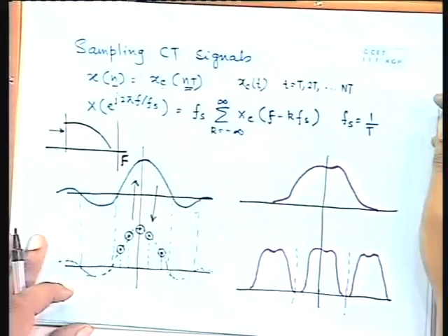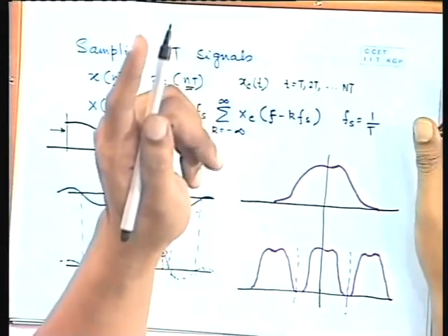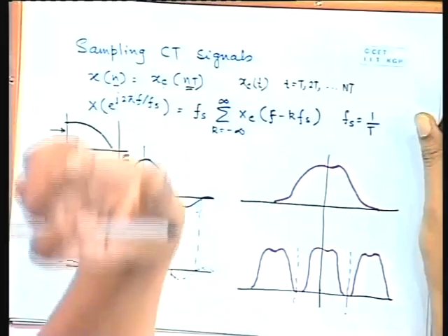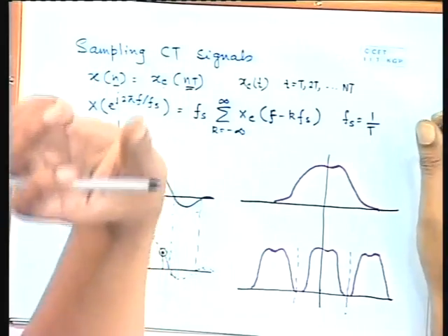The second thing that you have to do comes after that. Now that you have put an anti-aliasing filter, you know that its bandwidth is restricted. Now you can sample at twice the bandwidth or more. Practically speaking, you should do it at 5 to 10 times the bandwidth. But theoretically speaking, you should at least do it twice, so that the samples that you are getting are a faithful reproduction.